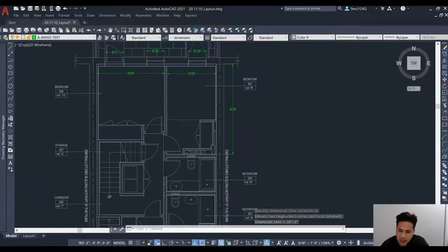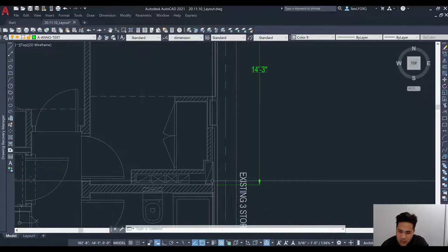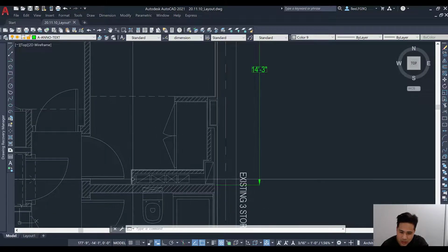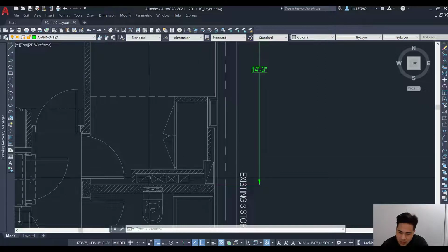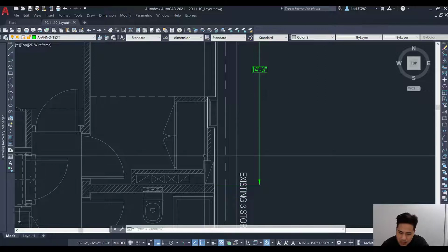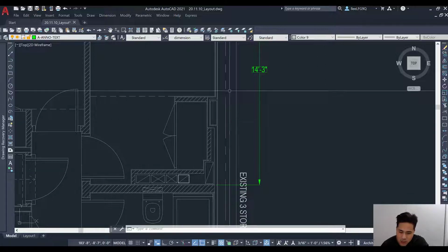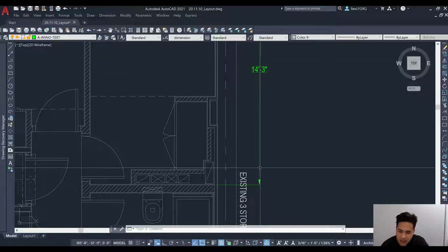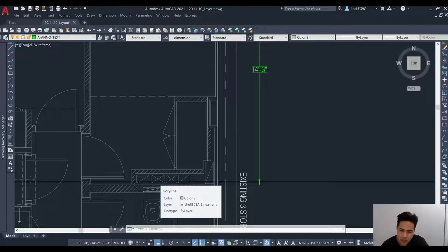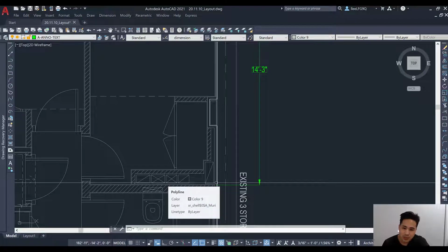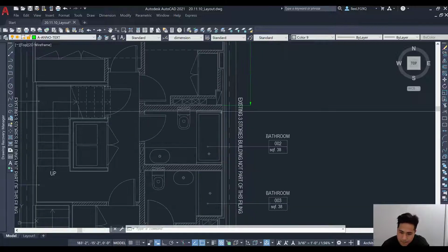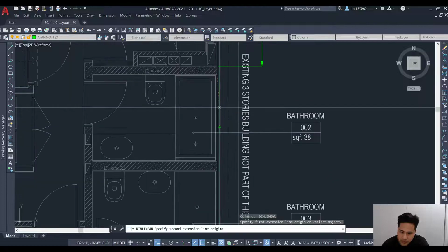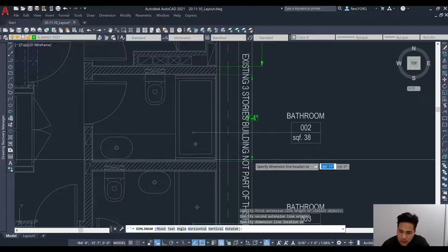And you see how here I simplified it by just extending it all the way down to this point, although there is a shaft here. Okay, some sort of opening here where it could be pipes, ductwork that are boxed out and enclosed. Just to simplify, we are going to provide a length, and usually if you want to simplify, you want to add more than less into the load calc. So we're gonna include the shaft into the length, and then we're just gonna go down the whole thing.